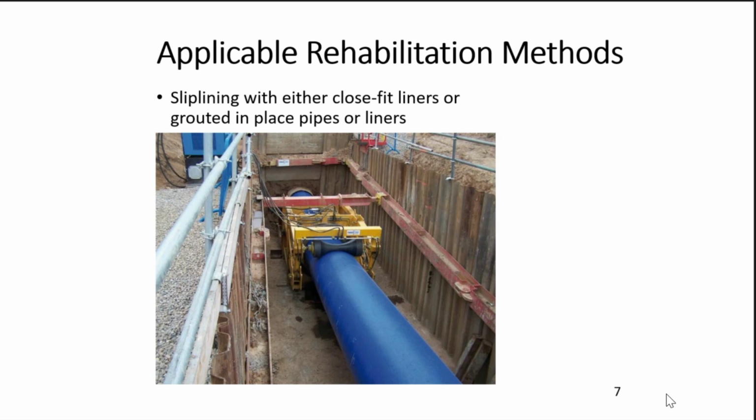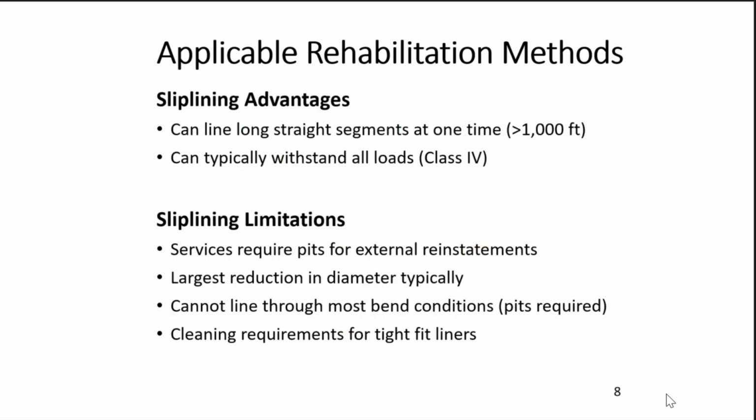There are various ways to take a pipe and temporarily reduce the diameter, insert it into a water main, and then let it expand back up. Or you can just install a pipe that is physically smaller inside of a host pipe, and then grout the outside, similar to the spiral lining. Again, a benefit with this is you can technically get an actual pipe inside of your pipe.